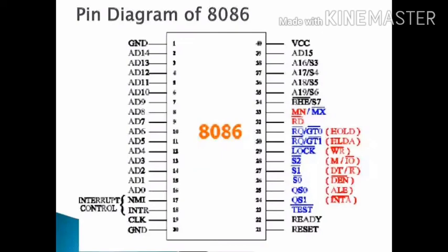If these pins are used for taking control over the local bus, and if a bus request comes at the same time from two different local bus masters on the pins, then the bus will be granted by the 8086 on the request 0 or grant 0 pin.